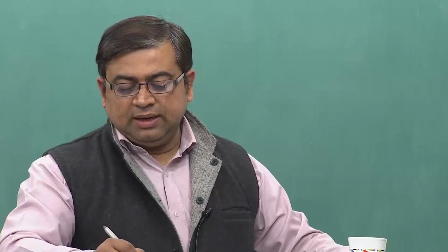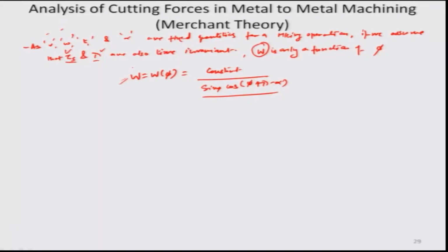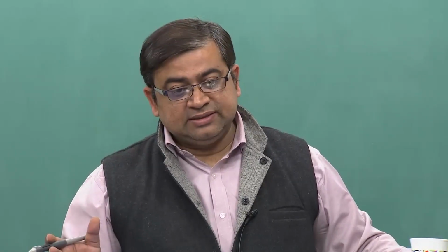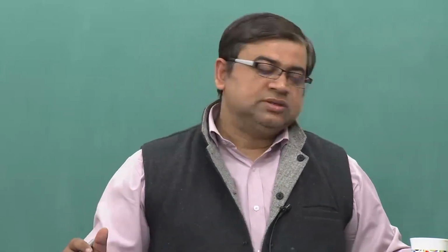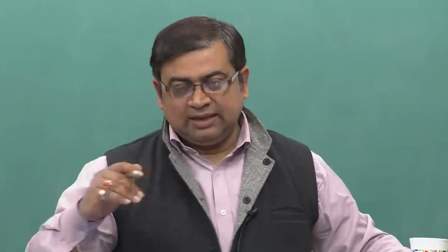So, basically we have to minimize the total amount of power or work done per unit time with respect to phi, and see at what phi values this power consumption would be minimum, or the angle would formulate in a way as if the cutting action is happening through the least path of resistance being offered to the tool surface, which is otherwise scraping through the material to remove it.